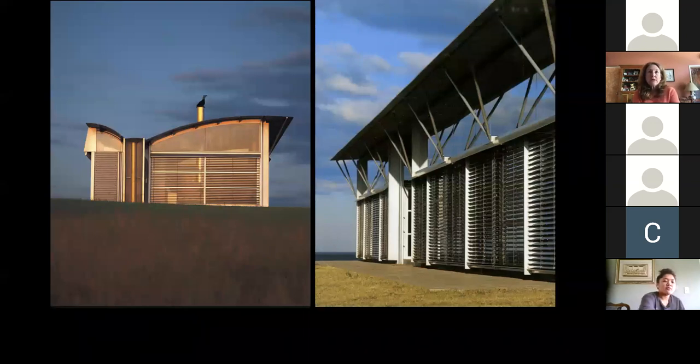So here you see the picture on the right shows the north facade, again, like our south, and it's designed with a lot of different layers. So at the very top, you'll see this upper clerestory window, and that is great for bringing in a lot of natural light, and it's shaded by a very large overhang that is designed to provide 100% shade in the summer, 50% at the equinoxes. You know how to do that. You're doing that now in your design projects.